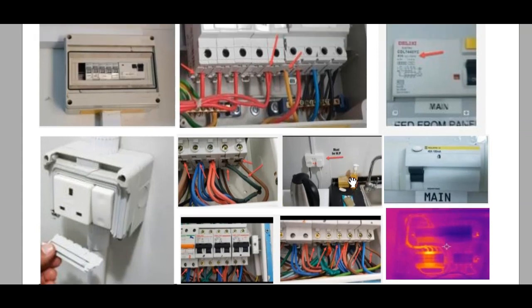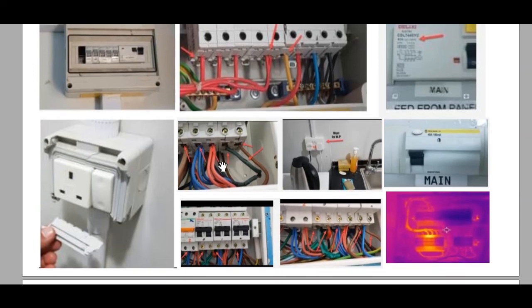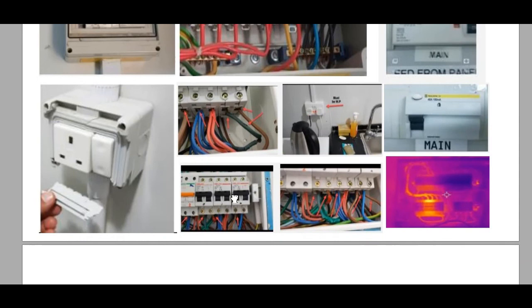Here this is a kitchen, and they used a normal type of socket. We must change it to the waterproof type. Here also they don't use bootlace ferrules. They don't use a numbering system. As you see, each two wires go slipping inside and are then tightened by the screws. This is not an electrician's work. And you see here also this black wire is overheated and will be damaged and cause a dangerous condition. This is a damaged wire, it must be changed.